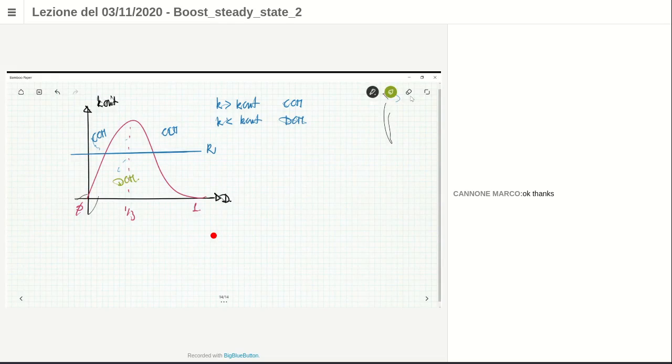Okay, so you operate in CCM around 0 and around 1, and around 1/3 you are always operating in DCM. So depending on the value of K, which is QLFS over R, this is K, typically you have CCM operating modes for lower range of D, DCM around 1/3, and then increasing D you go in CCM. Okay?